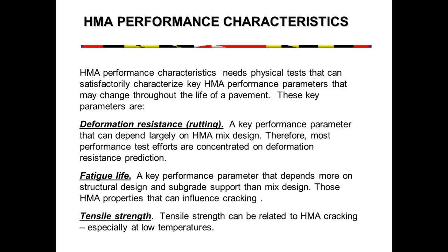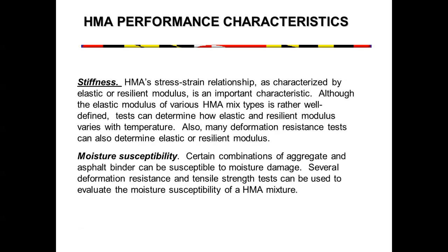Then there is low temperature cracking. For that, we need some tensile strength testing. Stiffness is a very important property of a material, especially for materials that are being used as structural material. This HMA stress-strain relationship, we characterize the stiffness of this HMA by using elastic or resilient modulus.